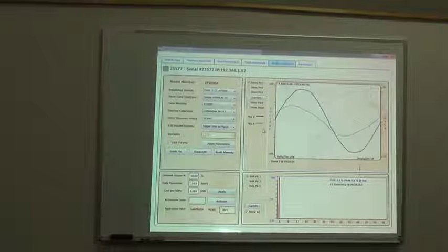We had one of our CTs backwards, so we just turned the panel off, fixed it, turned it back on, which is a little safer. Right, exactly. But not all facilities you're going to be able to turn that off. Well, CTs, to be honest with you, what you should do is put the banks in off mode, but you can disconnect and reconnect CTs, it has no effect. CT is low voltage, you can do that.